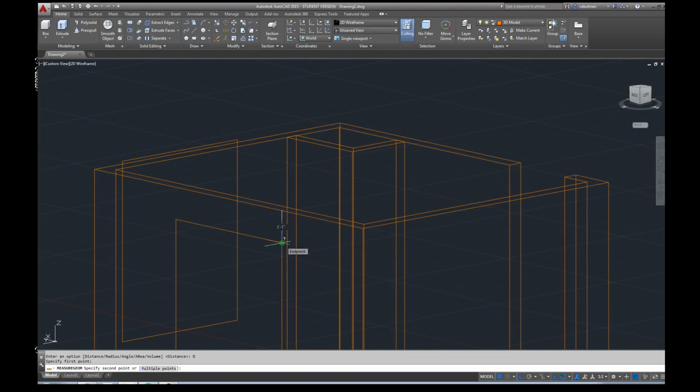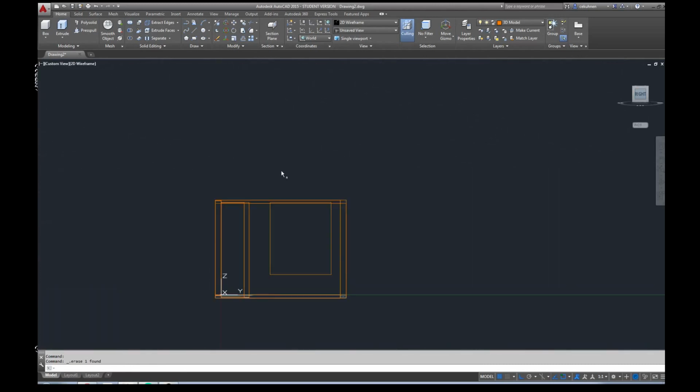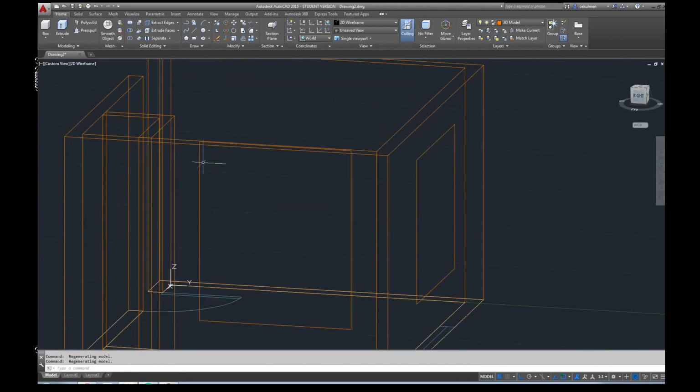So you see it's 1 foot and 1 inch. So here, for example, now select this rectangle, click and drag, push it down, and make myself from this point simply a line that is 1 foot and 1 inch tall.